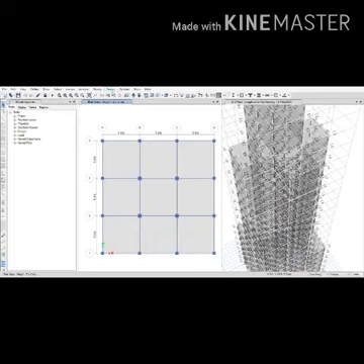Going to the design menu, you will find the concrete frame design. You have to review or revise these preferences, as the design code must always be IS 456 2000. Also after this, you have to go to start design check, and it will take some time.